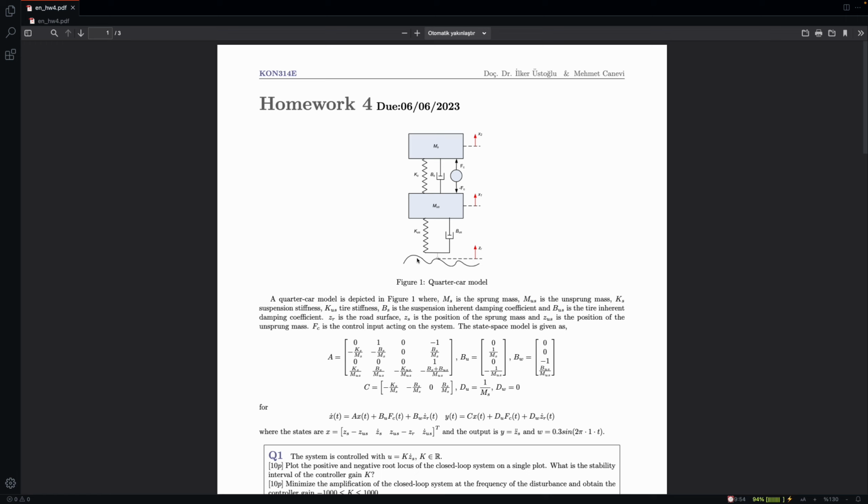Now, since this is the road, it touches the tire. This is basically the tire model. We will have a mass spring damper system that models the tire. Because it is an elastic material, we need the spring and damper in order to give basically the tire feel here. So it's a basic model to model a tire. Of course, this is not the most realistic one, but it is used commonly, so we've also opted for that.